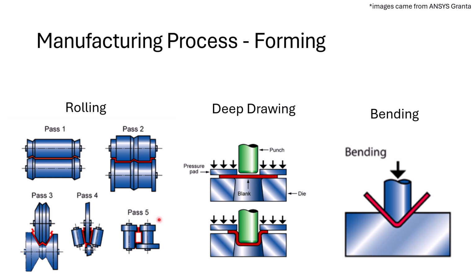There's deep drawing, so that's going to be similar to blanking and punching, but you're going to actually let the material move to form a little bit. Rather than just straight punching it out, you'll allow it to be drawn in. So this would be something more for maybe a soda can. You're going to start with a flat piece and draw out that whole cylinder. Maybe those CO2 cartridges, something like that, would also be drawn out. Maybe not for those, because you're probably going to want a little deeper, thicker wall thickness, but something like that where you really need a long, thin cylinder wall.